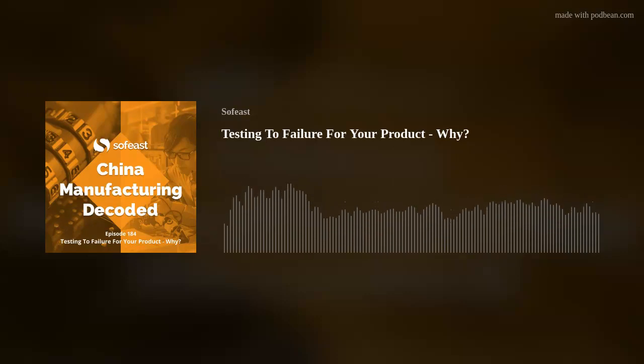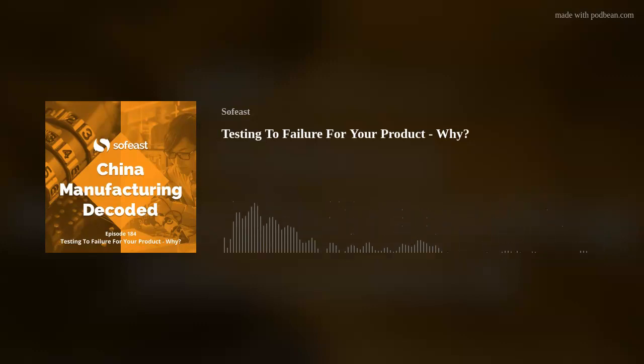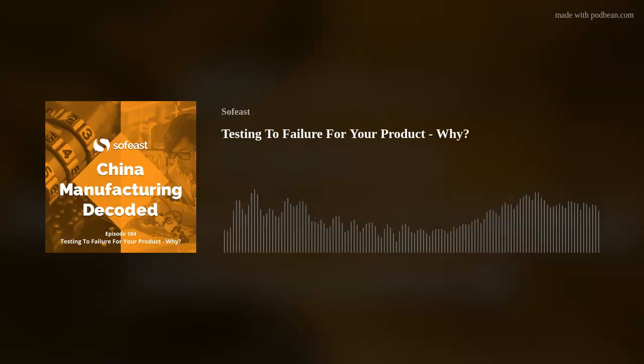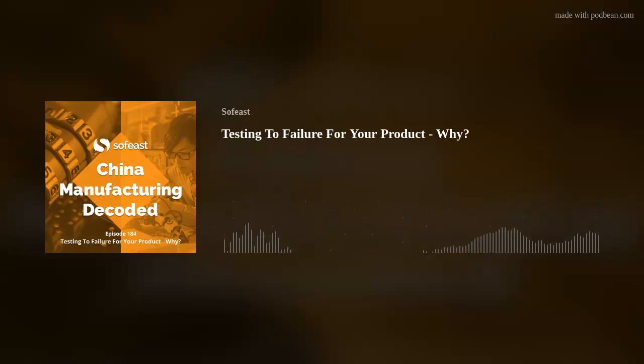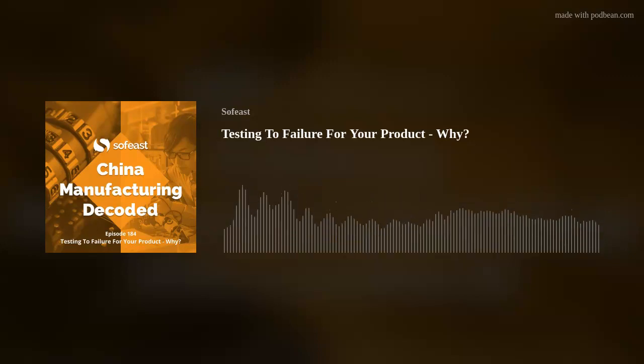Yeah, that's a great question. So one simple methodology is just doing a room temperature test and pushing the limits of your design. That could be voltage and current, just to see what happens. This will be a starting point, and you could do that on your bench test while you're designing your product.